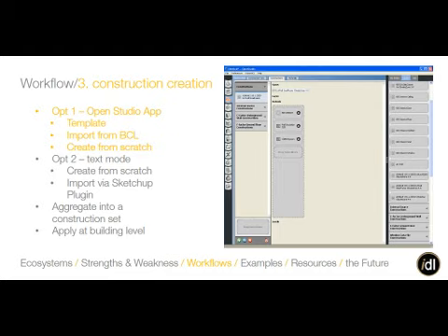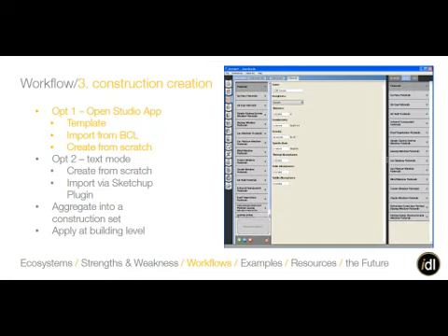This is the construction tab. This is like your sandwich layer of materials. You can click into your materials tab and see everything here. And then this is how you define specific heat, density, insulation values, and stuff like that. And this is a lot more input for each material than you get with some unidirectional heat flow programs like EQuest or HAP. That's because it's really trying to calculate the thermal mass balance of the materials as well. So you really get that thermal mass effect embedded within the heat calculation engine.